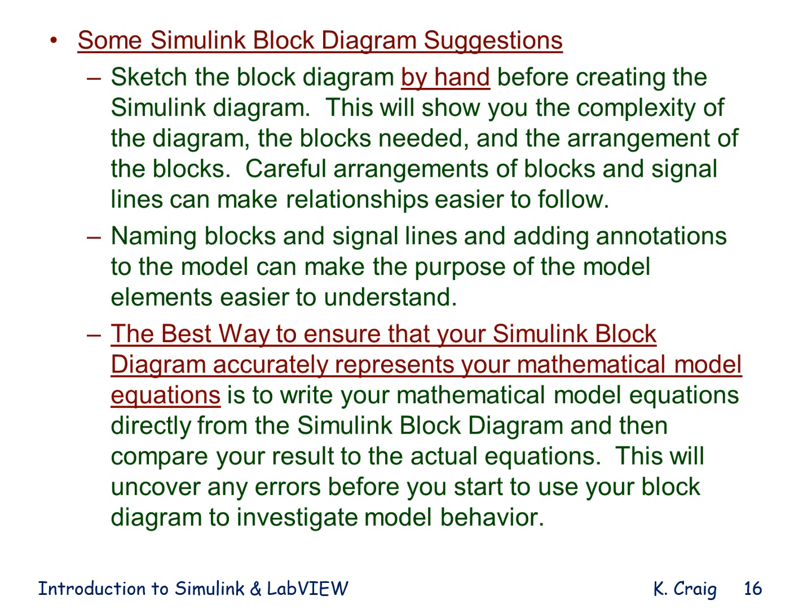Lastly, the best way to ensure that your Simulink block diagram accurately represents your mathematical model equations is to write your mathematical model equations directly from the Simulink block diagram, and then compare your result to the actual equations. This will uncover any errors before you start to use your block diagram to investigate model behavior.